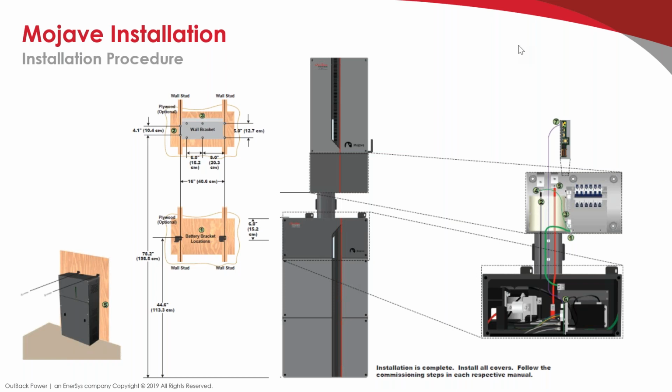I depicted as number 1. There's a bond there, negative to ground bond. That used to be a field cable that had to be wired, but now that is done at the factory. So that is one less item that you would have to wire in the system, and we're going to be updating the documentation, but just to give you a heads up, that's just one less thing that you have to worry about.